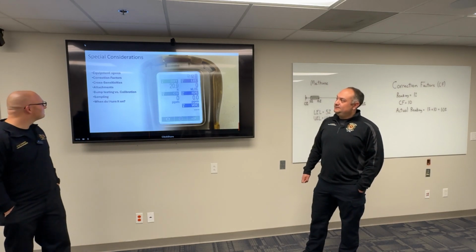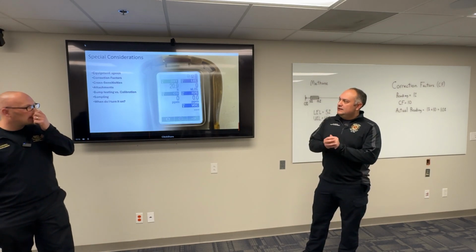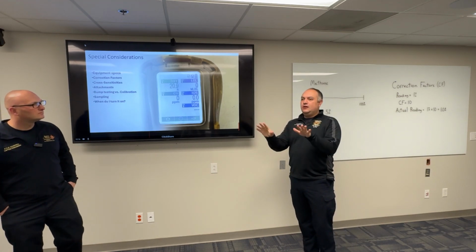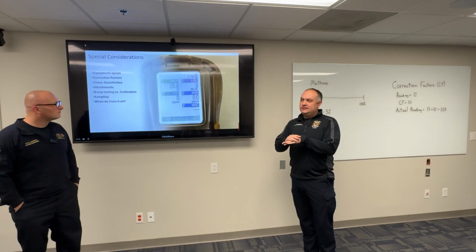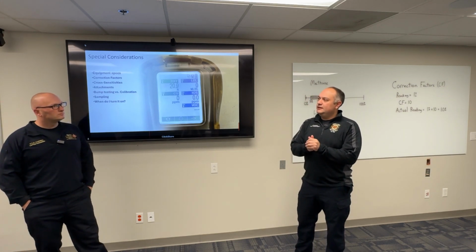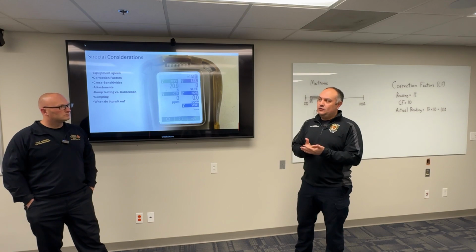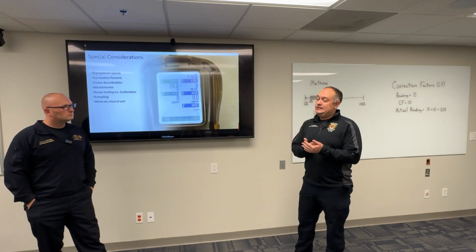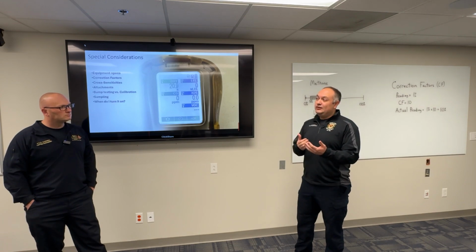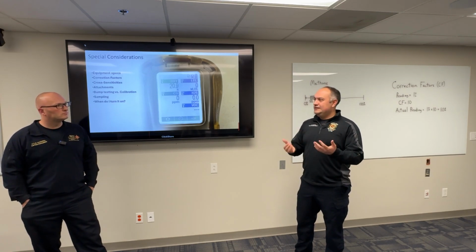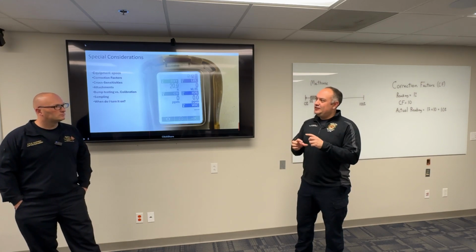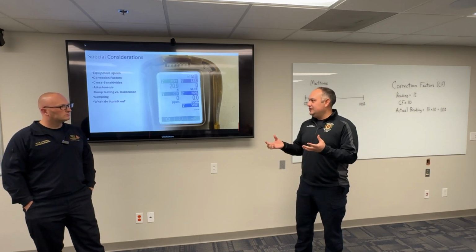Potentially. Tell us about some bump testing and calibration. So we're talking about bump testing. Technically, if we're speaking on OSHA and regulations, you're supposed to bump test your 4-gas meter or whatever monitor you're working with before you use it, just to verify that it is working correctly and it's seeing what it should see. Bump testing is what's called a qualitative measurement. So basically it's a yes or a no. It's not really accurate. We're not talking about numbers at that point, in simple terms.